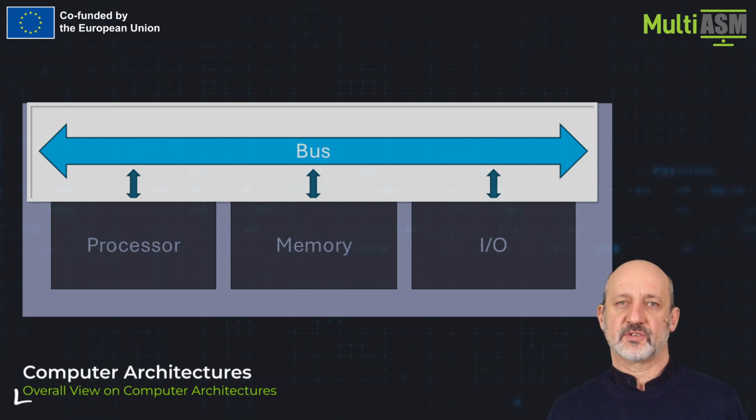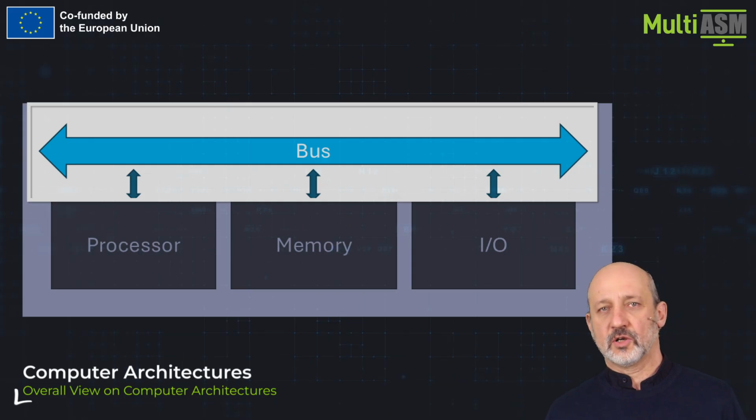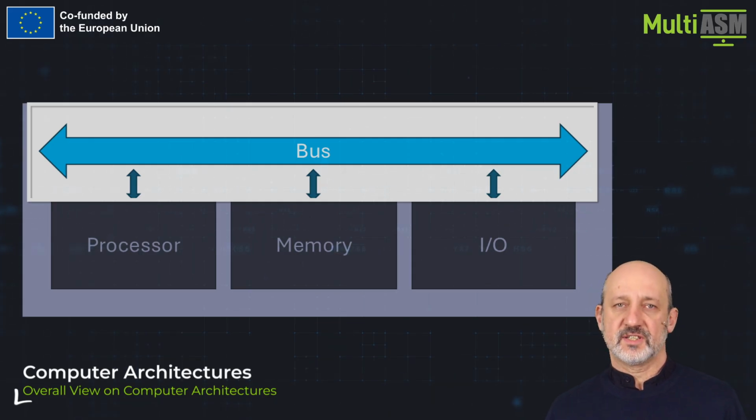at the specified address. The control bus also can include other signals specific to the system, for example, interrupt signals, DMA control lines, clock pulses, signals distinguishing the memory and peripherals access, signals activating chosen modules, and others. As you will see in the following videos, there will be many variants of each of the elements we discussed: processors, memory configuration, and buses.